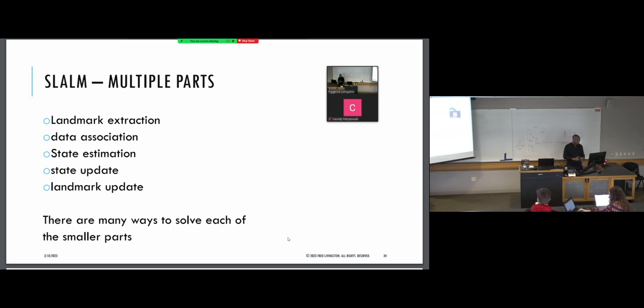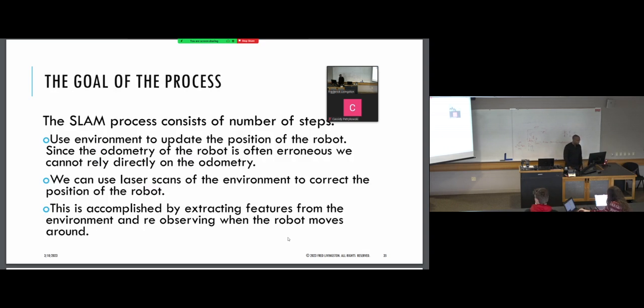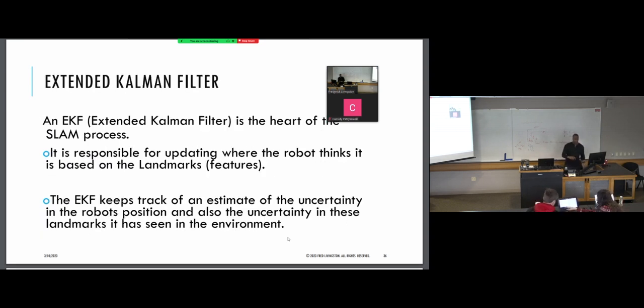And we need to estimate our position on that, and we're going to go through this in more detail in a little bit. We're going to use the laser scan; we can subscribe to that topic. We're also going to use the IMU and the odometry information, which is the estimated position based on velocity information from the IMU. How well it does that estimation depends on the quality of the IMU. We can use an algorithm called the extended Kalman filter to give a better estimation of where you actually are in your system. There's a lot of error and noise in these systems, and the Kalman filter is going to kick out that noise to make it a better estimate of your true position in space.